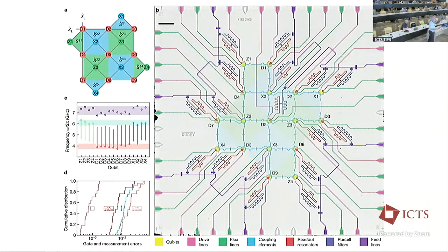If you zoomed in on them, they're so-called interdigitated capacitors, but they're places where the transmission lines are interrupted. So indeed, that's an aspect of the electrodynamics. You have a long transmission line, carrying radiation of course, surrounded by these ground planes.